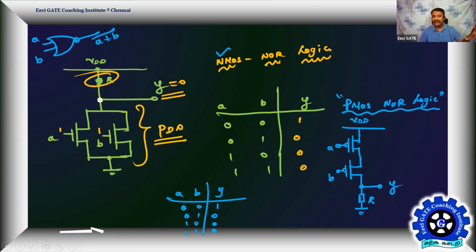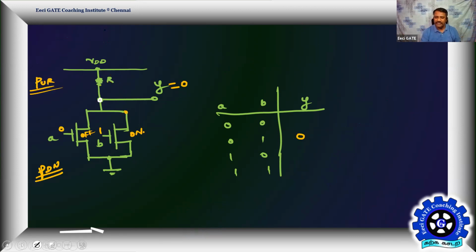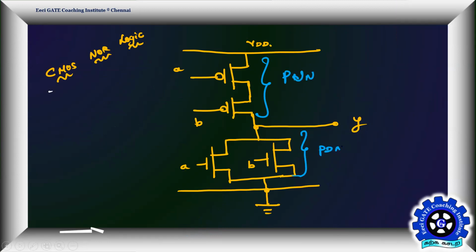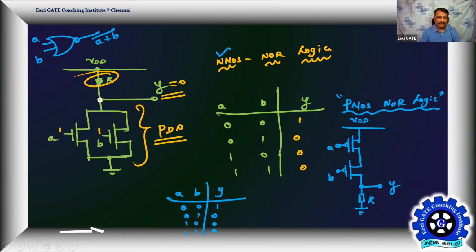Now you separately make NMOS design and separately make PMOS design, replace the two resistors. That's all. That is going to become a CMOS implementation. You know what is your pull up, you know what is your pull down, then club the two, result is your CMOS. Easy, everyone. It's up to you. If you feel CMOS is complicated, first separately make NMOS logic and then separately make PMOS logic and simply replace pull up by PMOS, replace pull down by NMOS. That's your CMOS logic function for the same logic function, whatever you are implementing.